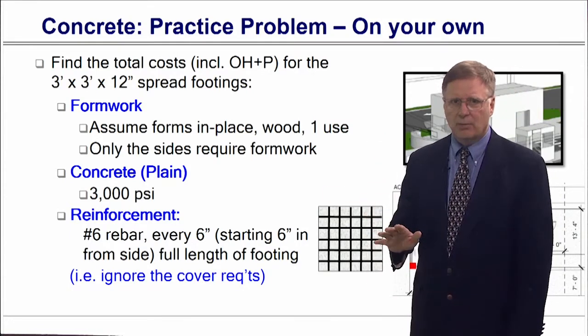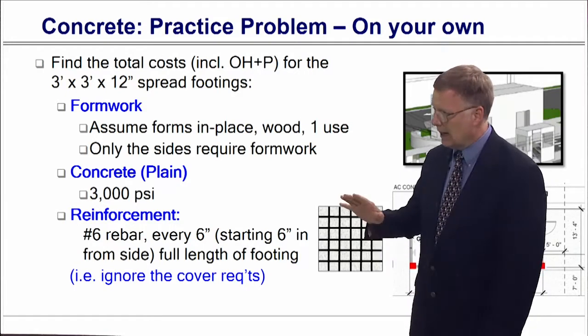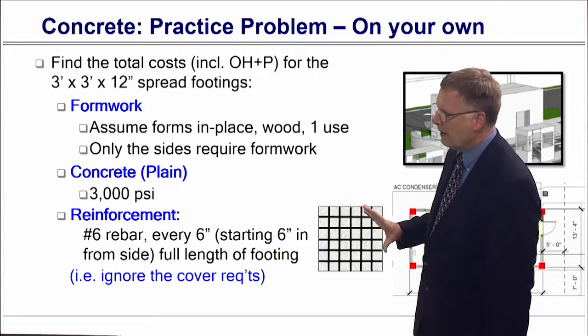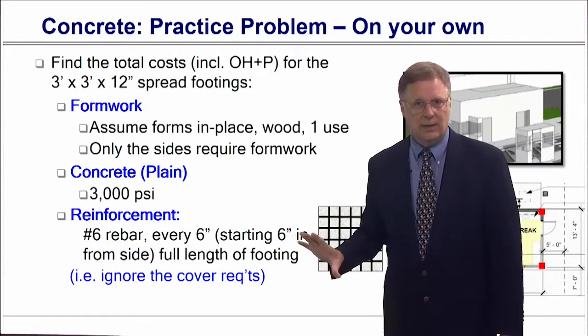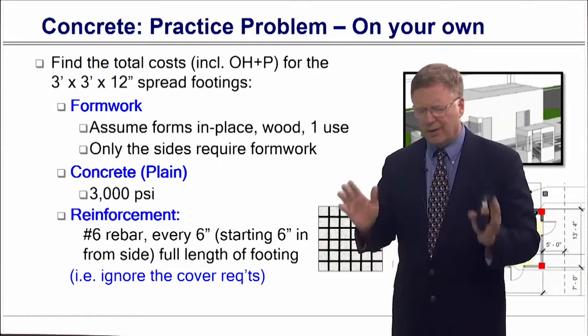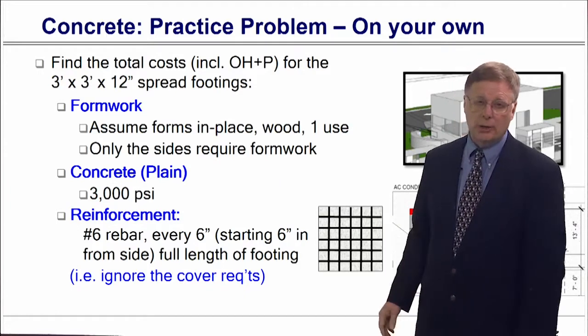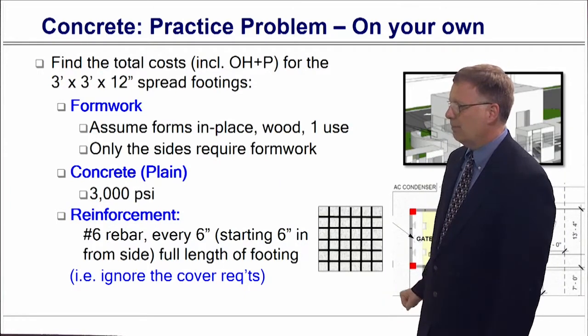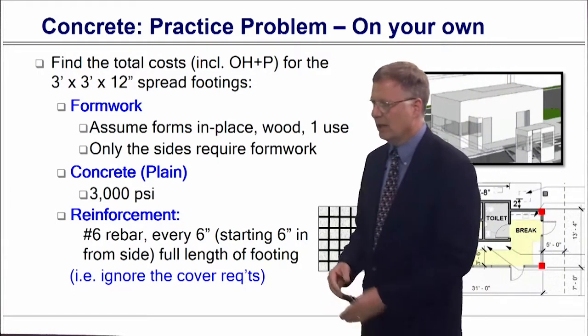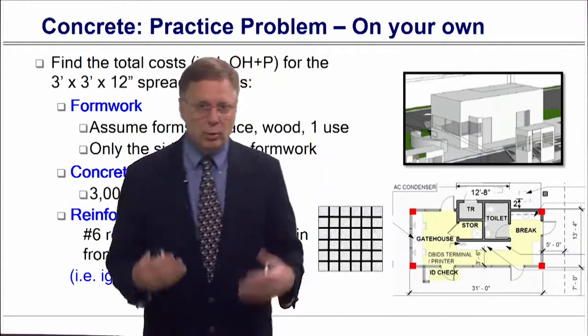So the civils out there are probably having heart palpitations. I understand, okay? But we're going to price it without the cover requirements. Obviously in design, you're going to worry about that. But in the pricing, we're not going to do that. So you can count how many rebars and the length of the rebars and everything. It's going to go in both directions.